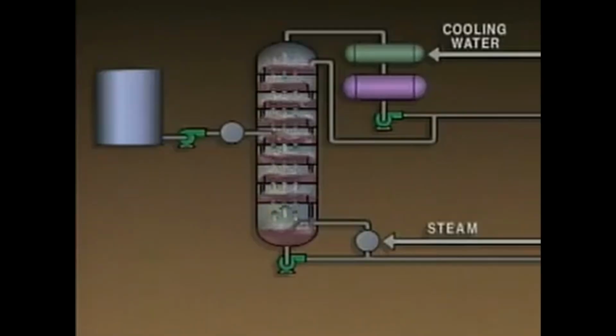Temperatures in a distillation system are typically controlled in three ways. One way is to control the temperature of the feed mixture by using a preheater. This regulates the temperature at the feed point. At the bottom of the tower, temperature is controlled by the amount of heat that is added by the reboiler. This added heat is referred to as boil-up.